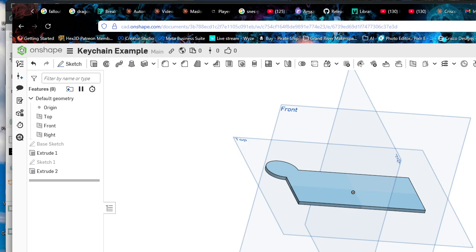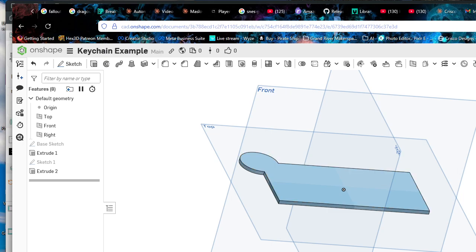Now you can do some advanced things, and there's parameters you can add. So if we knew we wanted to define things by thickness, I do this with laser cut projects quite a bit. You could define a variable called thickness, and I could change the variable that says thickness is 1/8 inch. Then if I change a design for 1/4 inch, I could type in the new thickness and it would automatically generate the design if I have everything fully defined. If I don't have things defined, what you see here will happen. I'll change one thing and then some things won't change with it.